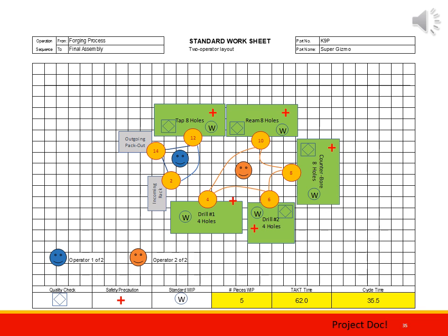If the cycle time was exactly 31 minutes, if I do this right, then a cycle with 1 operator would be 62 seconds. I'm sorry, did I say minutes? Bad me, seconds. If the cycle time was in quantities of 62, let's say it was a 31-second cycle time, which would mean for 2 people, with a 1-person playbook, it is a 62-second cycle time, then my cycle time meets takt time and 1 person can be in the cell. But rarely does it work that way. It can, but rarely. So in this case, I have to have 2 people in the cell.